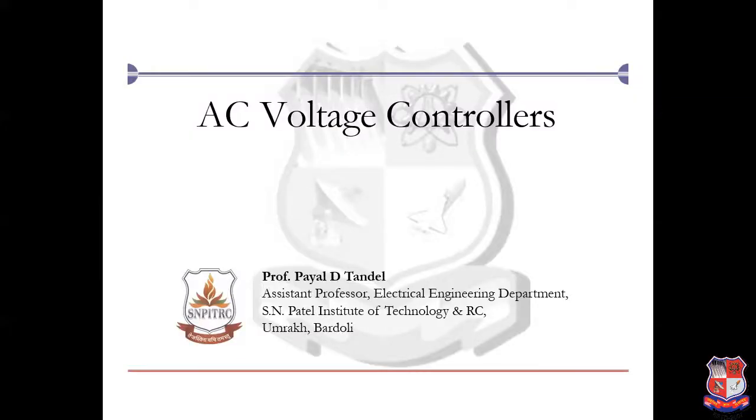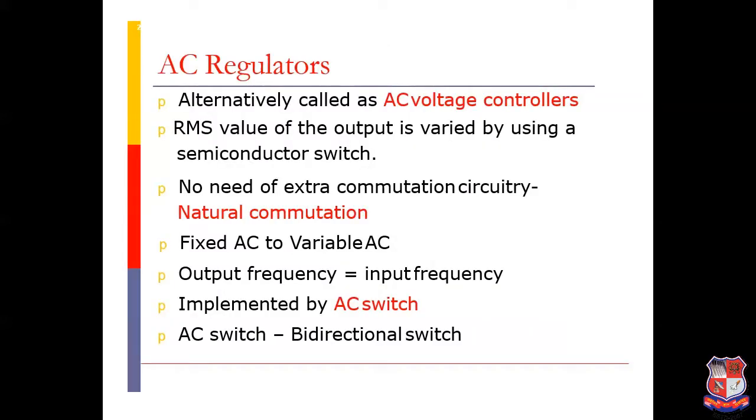Welcome you all. Today I am going to deliver a session on AC voltage controllers, which are also known as AC regulators. So first of all, let's discuss what is AC voltage regulator and the requirement of this converter. AC voltage controllers convert fixed AC quantity to variable AC quantity by keeping the frequency constant.